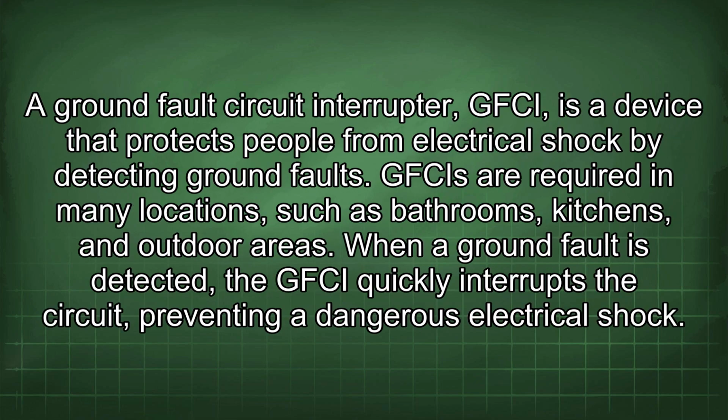A ground fault circuit interrupter (GFCI) is a device that protects people from electrical shock by detecting ground faults. GFCIs are required in many locations, such as bathrooms, kitchens, and outdoor areas. When a ground fault is detected, the GFCI quickly interrupts the circuit, preventing a dangerous electrical shock.